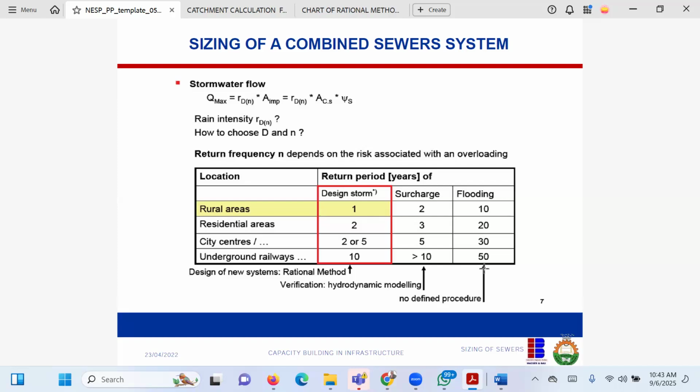That's why securing underground infrastructure is very key. Because imagine when it floods underground, the whole electrical devices, the whole sensors, everything I've invested on underground. In fact, it could even submerge, and there could be, what do you call it, subsidence, where the whole place will collapse. So underground systems must not flood. So hence, we increase the safety factor to about 50 years. Yes, you can say these represent more of safety factors. But those safety factors will now determine the type of rain we are going to use to design your runoff.